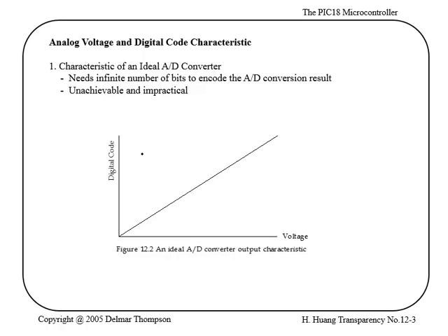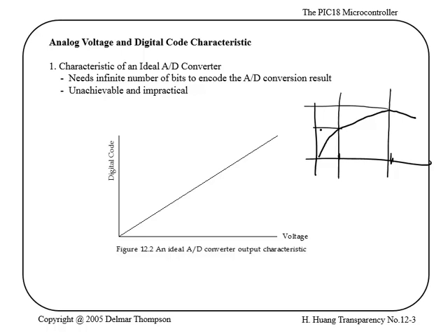So if you look at the elements that are sensitive to, for example, pressure, take a piezoelectric unit, it's not going to show you a linear behavior, right? So the behavior could be something like this, and it's only going to be one section of it that is going to be linear. So basically the manufacturer is going to say, I'm going to map from this value to this value, and this is the only place that I can guarantee linearity. Outside of that, I don't guarantee that my device is going to work. So you're going to find in the electrical characteristics of the devices that in one region, you're going to be linear. So that's one part.